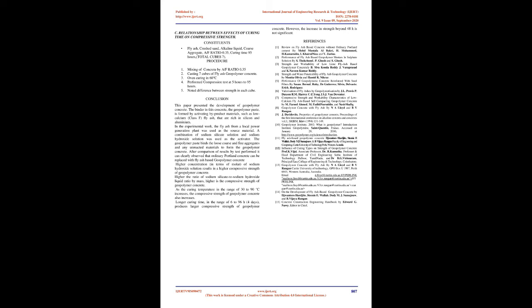Of course, all aggregates should be clean, that is, free of impurities such as salt, clay, dirt, or foreign matter. As a matter of convenience, aggregates are generally divided into two size ranges: coarse aggregate, which is the fraction of material retained on a number 4, 4.75 mm, sieve, and fine aggregate, which is the fraction passing number 4 sieve but retained on a number 100, 0.15 mm, sieve.